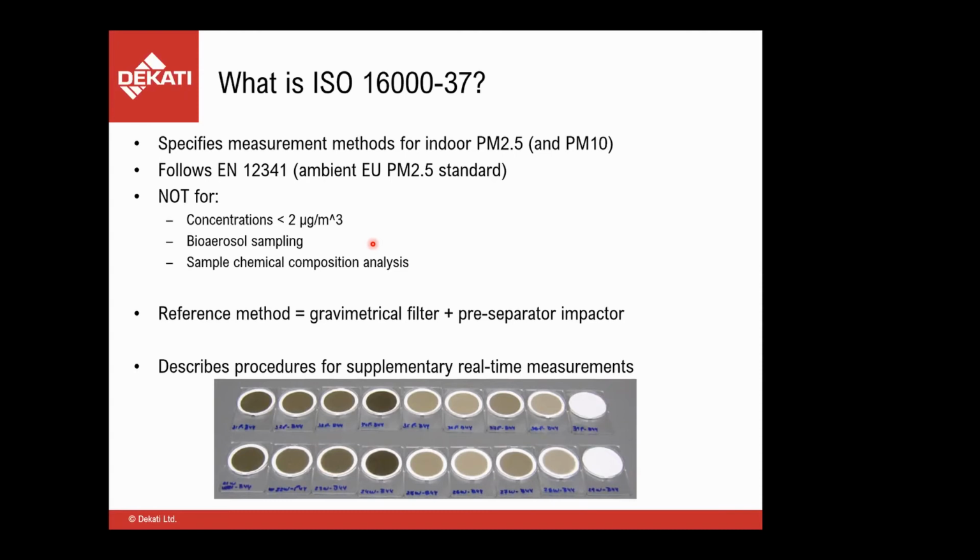The reference method is fairly simple. So we have a gravimetric filter and a pre-separator, which is as defined in the EN 12341. In addition, it describes procedures for, as said, supplementary real-time measurements that help in understanding the data.